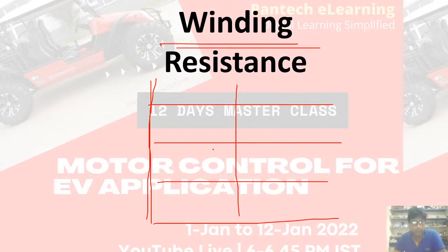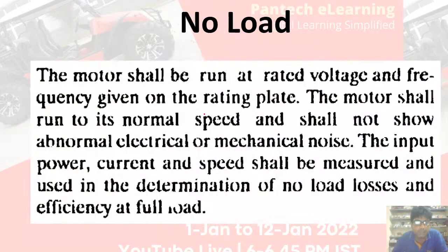Sorry. So the winding resistance will be checked based on the data sheet of the machine, because it will predict the performance characteristics of the machine. So no standard will define that. Next is the no load test.